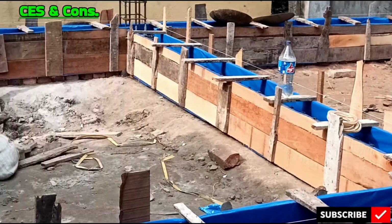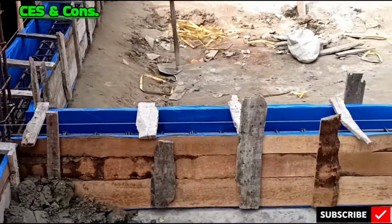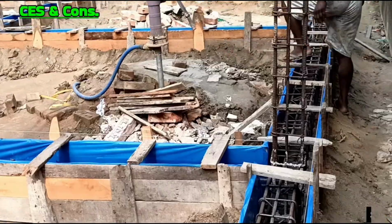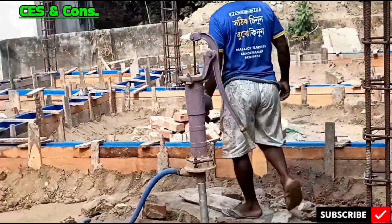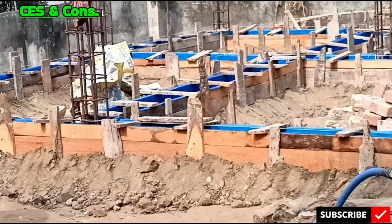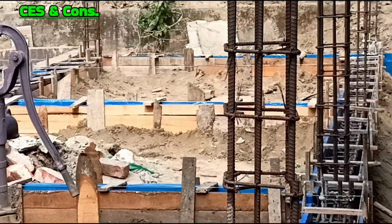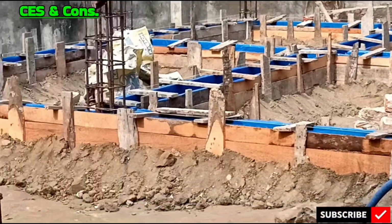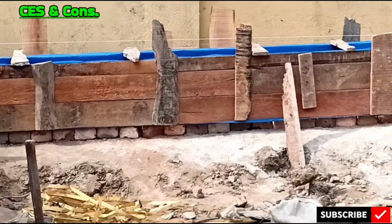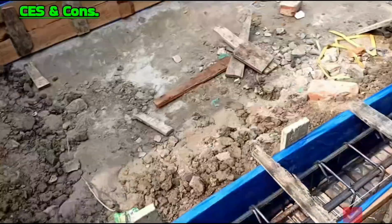A plinth beam is a must and a critical component in a building's foundation system. It is made of RCC, which consists of cement, sand and aggregate, and steel reinforcement bars. The steel provides tensile strength while the concrete handles compressive loads. It is constructed between the foundation and the superstructure, typically at the plinth level, that is above the ground level and below the floor slab. Plinth beams are used in load-bearing structures, frame structure with RCC columns and walls, and seismically active regions to enhance structural resilience. It has several utilities.